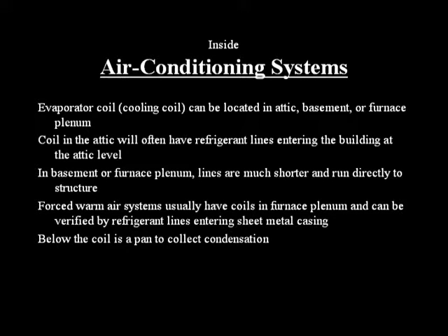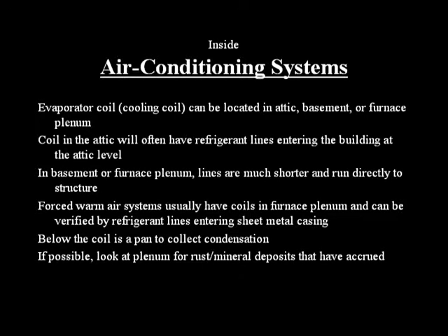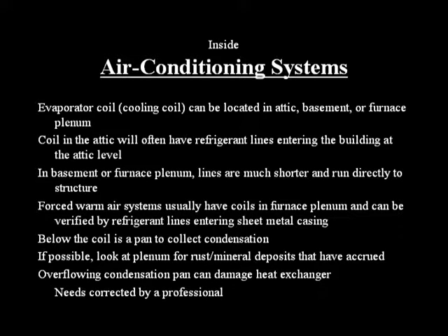Below the coil will be a pan to collect condensation and plastic pipes. If possible, look at the plenum for rust or mineral deposits that have accrued. An overflowing condensation pan can damage the heat exchanger and needs to be corrected by a professional. When the unit is operational, listen for unusual noises or vibrations.